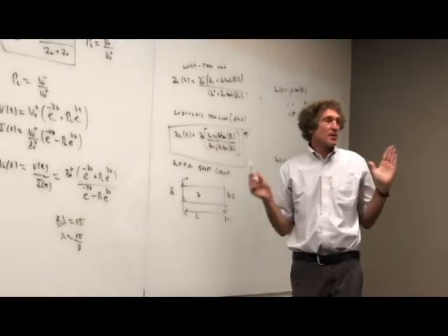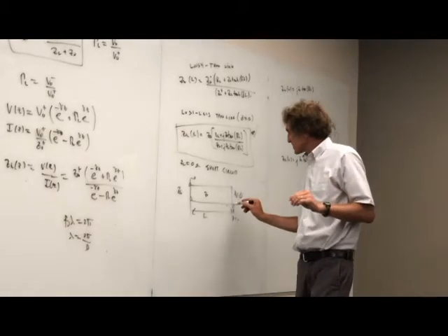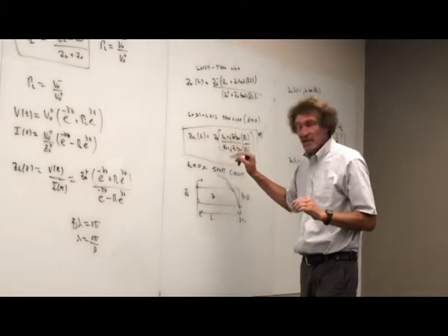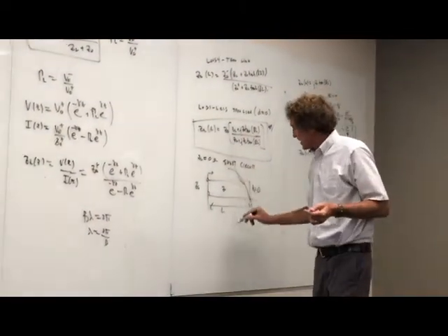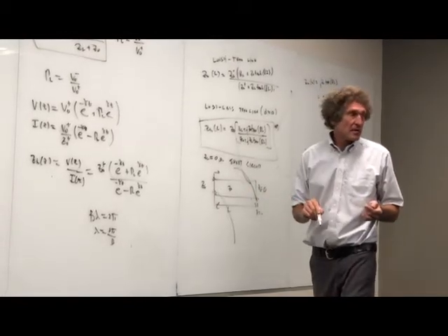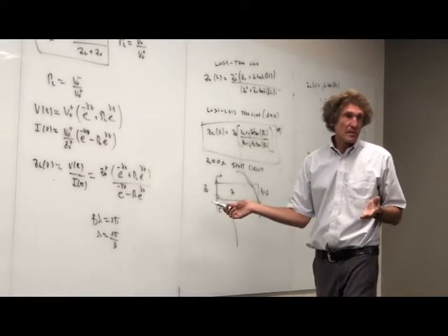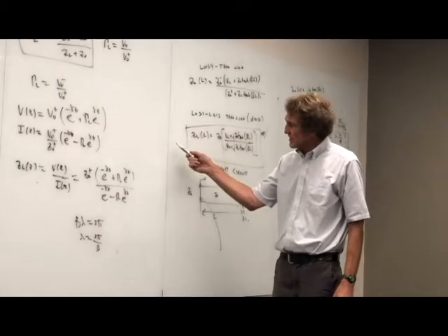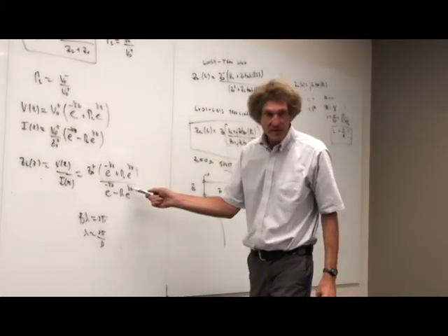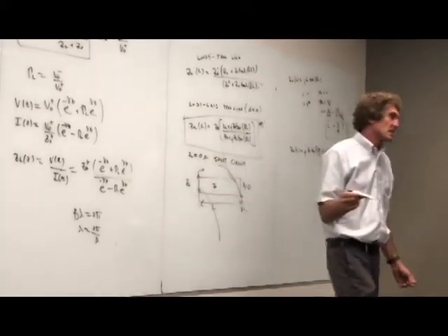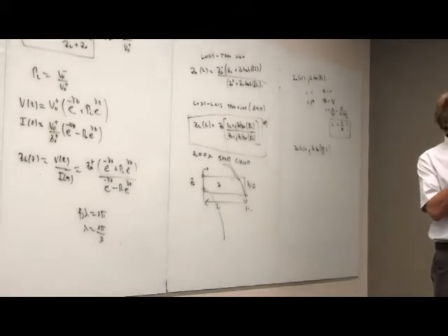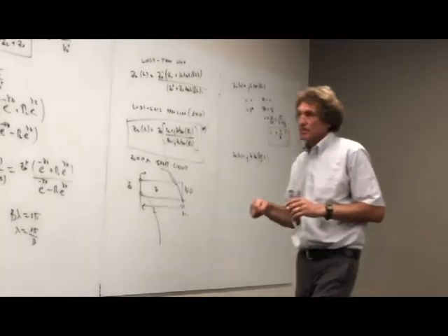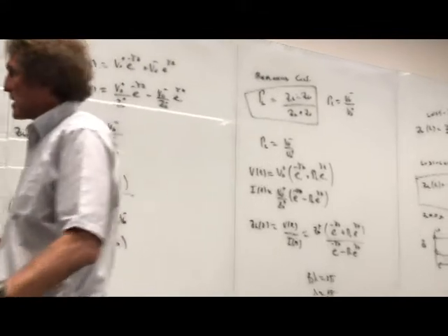And this is the one thing about input impedance. It's basically periodic in lambda over 2. It starts at 0 if it's a short circuit. It goes to a peak value of infinity, basically going to infinity at quarter wavelength, and then it goes back to 0 again when you're at lambda over 2. And then it repeats itself. Here it'll be 0, then it'll approach infinity, go to negative infinity, come back to 0 again. And that's the way impedance is actually seen versus length of cable if you short it. Now if it's an open circuit, it's the opposite. We're going to do that next, right here.